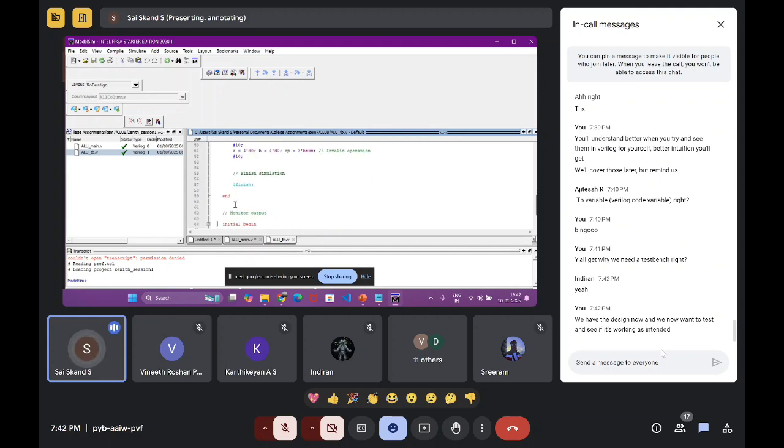So we are ending the initial block we defined, right? Begin should be ended by an end. And then similarly we are defining another initial block. Now this is the important thing: these two blocks, initial begin end and this other initial begin end, will be happening concurrently, simultaneously. That is the whole purpose of using a hardware description language. So we are simultaneously assigning values and at the same time checking the values.